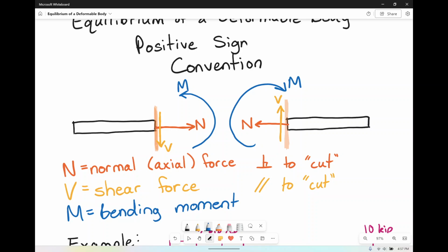So how would you solve for these forces? Well, obviously the exact same way that you do in statics. You just sum the forces in the x direction, sum the forces in the y direction, and sum some moments about a point. Which point would you take to sum the moments? Usually, we always take the point that is the cut. That is just the easiest, because then you don't have to worry about your shear force that you just calculated creating a moment, because if it did, and you calculated your shear wrong, then obviously your moment's going to be wrong as well.